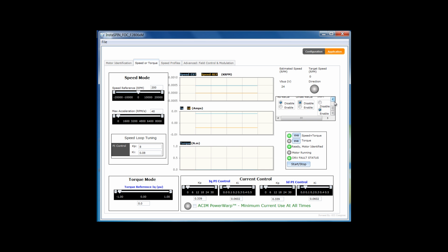This allows us to have a set point to where we force the startup initial rotation before our fast algorithm's feedback starts being used in the control system. And again, the user's guide, the quick start guide, has quite a few details on the capability and how you can change the set point of where this occurs. So with that, I'm going to go ahead and start up with all of the default values.